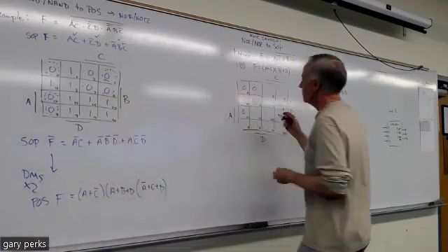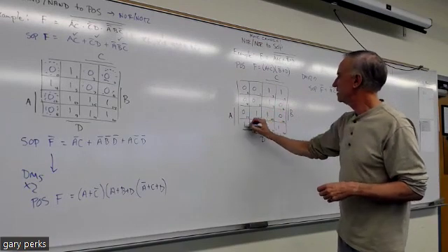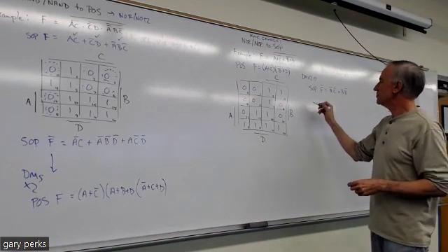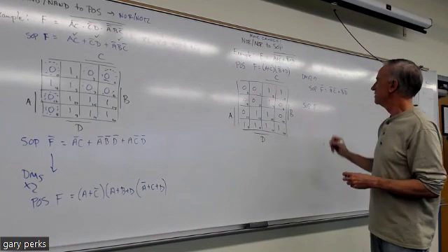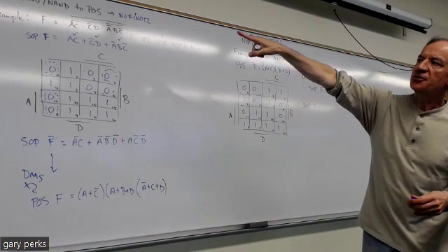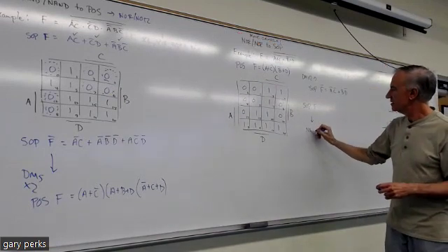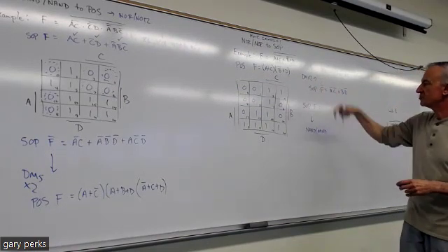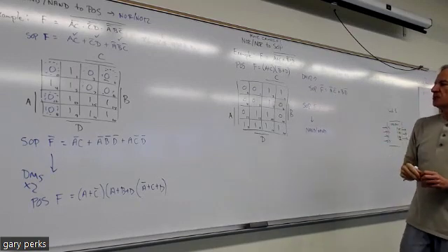All right, so where you don't have a 0, you have a 1. So fill in the 1s. And now, by circling the 1s, we're going to get the reduced SOP for F. And then once you have SOP for F, you could get the NAND expression, right? You could go from this to NAND if you wanted to. I mean, we weren't asked to do that, but I'm just pointing that out from what we did earlier.